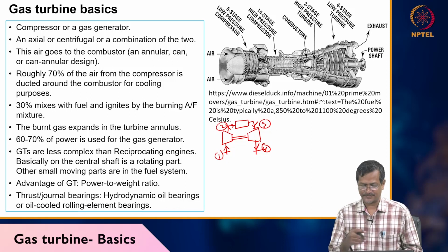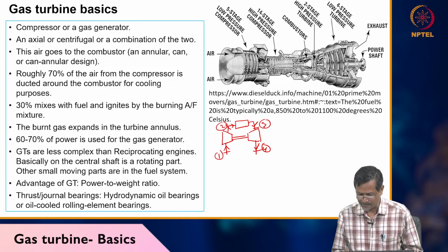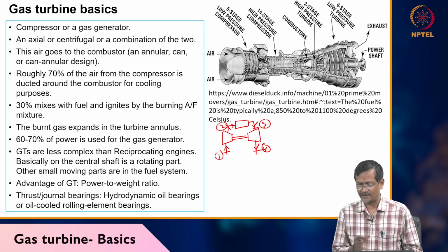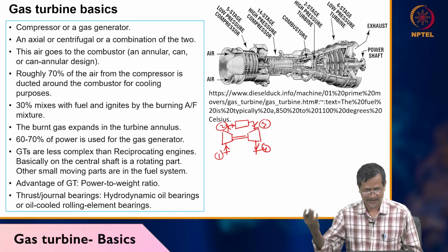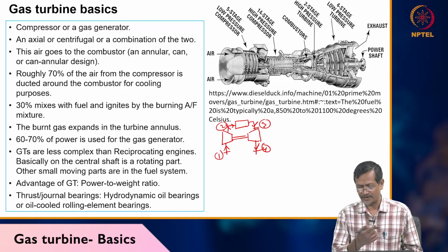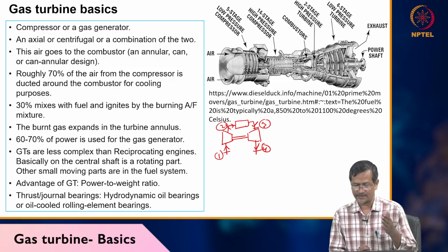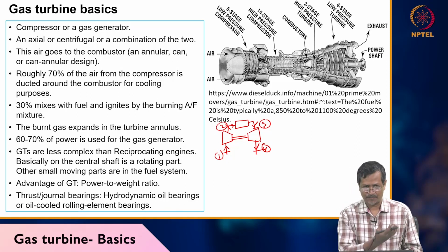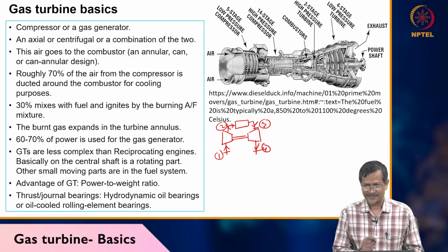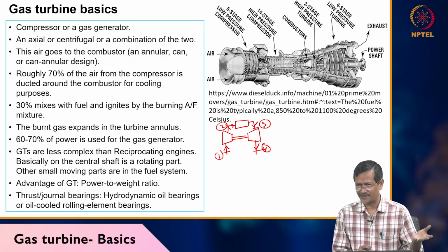In many cases, for simplification, people will be adding 4 to 1, but practically it does not happen, because the same exhaust gas, the burned gas that does not have any oxygen, you cannot put in the turbine compressor again. Another issue is that the gas will have a higher temperature, and compressing higher temperature gas is not suggested.